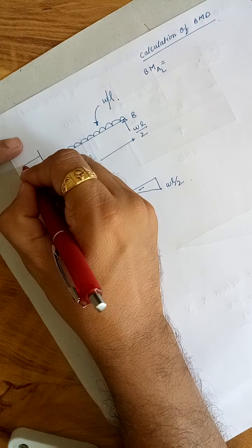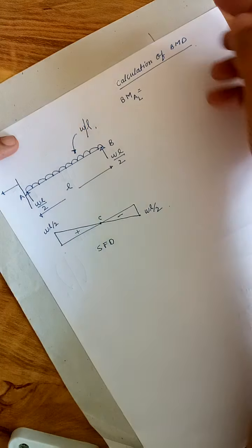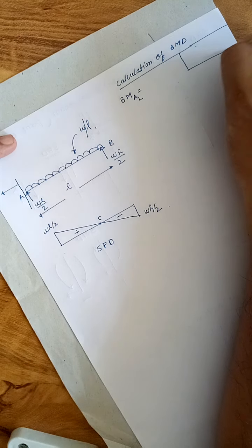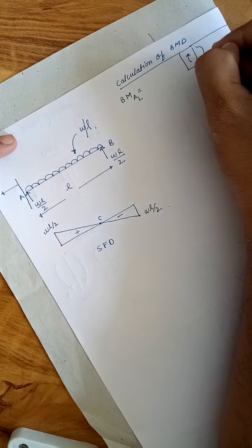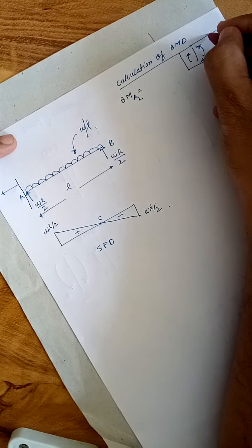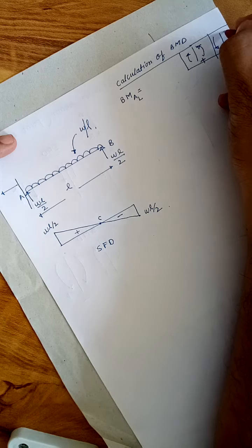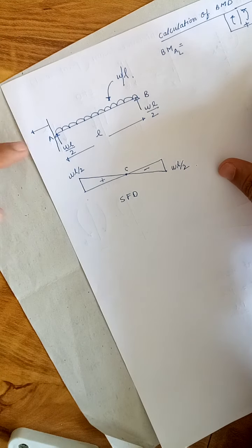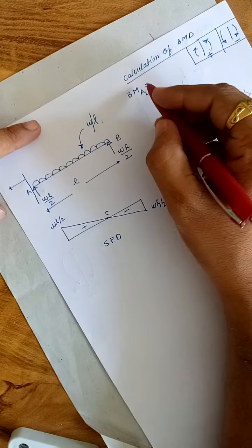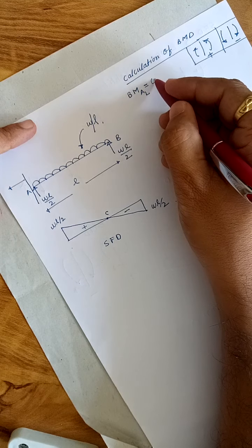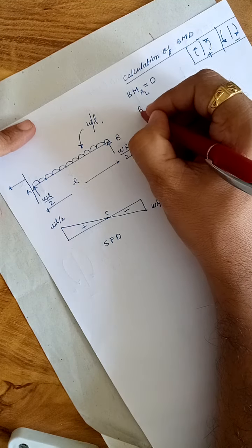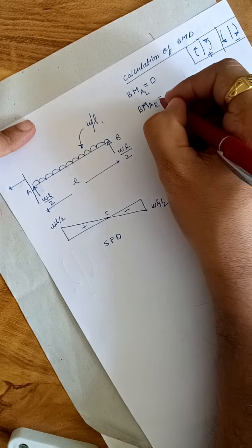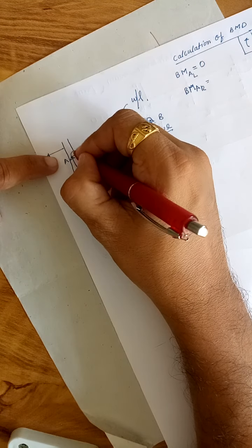At the left side there is no load, isn't it? And again important, that is the sign convention for bending moment. Like this, if it is, then it will be positive, and if it is like this, it will be negative. So at the left side there is no load, that's why there will be no bending moment at all, it will be 0 at A left. Now bending moment at A right, meaning I am considering the section at this point.